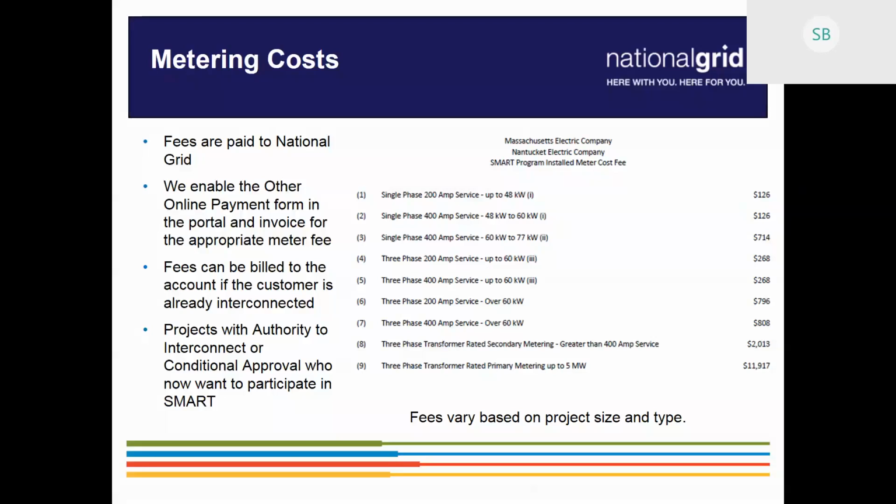So ultimately, there's no quota, right? The only quotas are for the programs of the Mass DOER, the SMART program. They do have a quota, right? But for under 25 kilowatt connected to three-phase lines, and under 15 kilowatt connected to single-phase lines, there's no cap on the net meter caps. So you can have as many of those as you like. But if you want additional funds beyond that meter, a SMART adder that Tara talked about, there's going to be limitations to that. But that's all set by underlying legislation, which the Mass DOER then turns into regulations, and then we eventually turn into tariffs, which the DPU eventually approves, and that's what we use going forward.